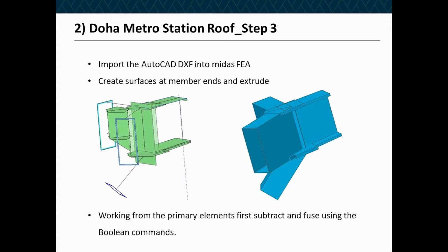We would then subtract and fuse using the Boolean commands within MIDAS FEA to actually give ourselves a single entity volume within FEA that we could then mesh.